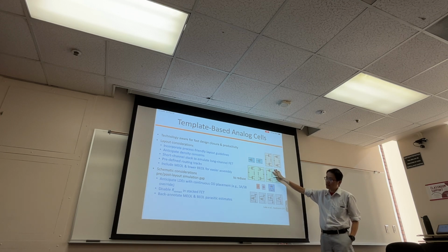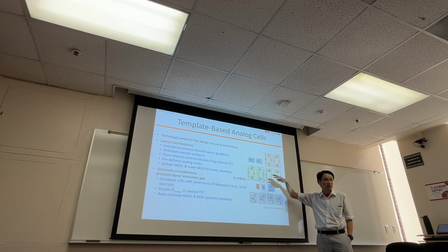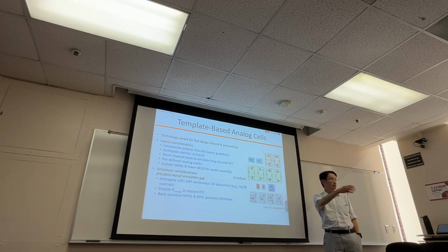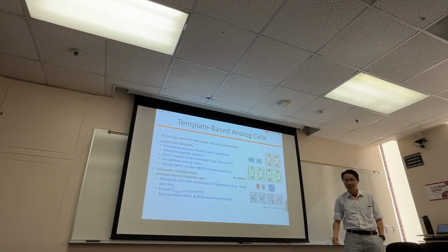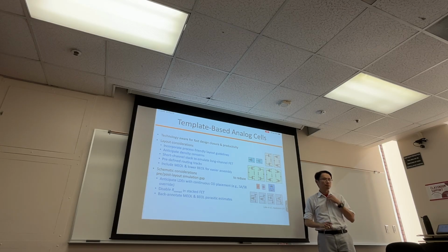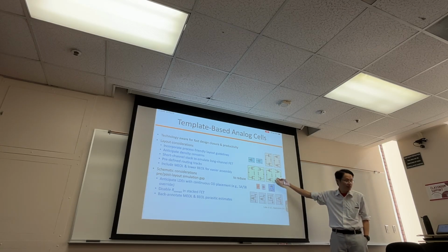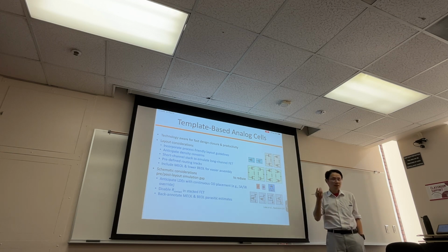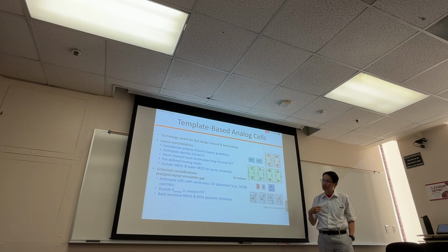And by the way, those are not just randomly designed templates. The idea of this template is that if you tile them up, you wouldn't violate any DRCs. Okay, so remember I talked about this density, right? You don't want some part to be too dense, some to be less dense. Usually when they design this, the density will be just right. Okay, so basically you have pre-made all these templates, and you know that when you pop them down, you tile them up, everything will come back just right.